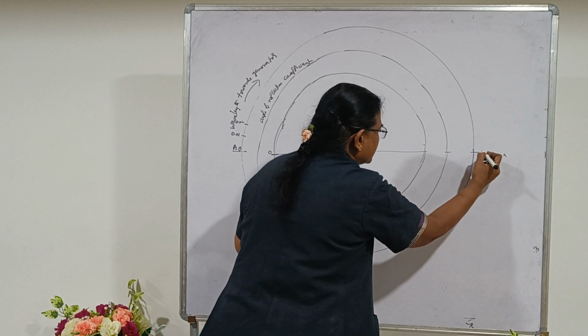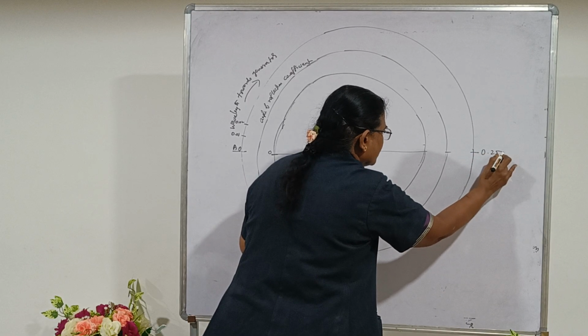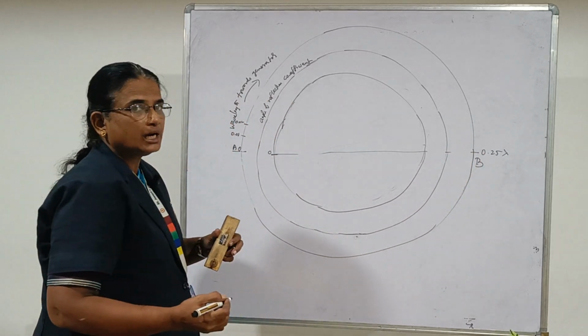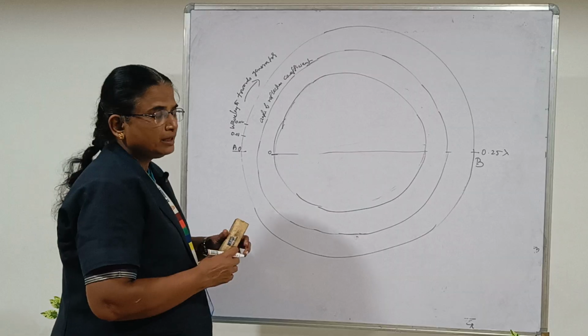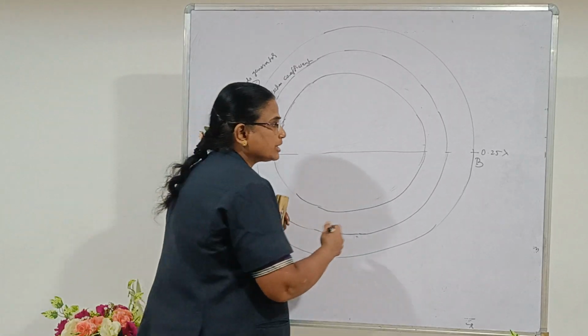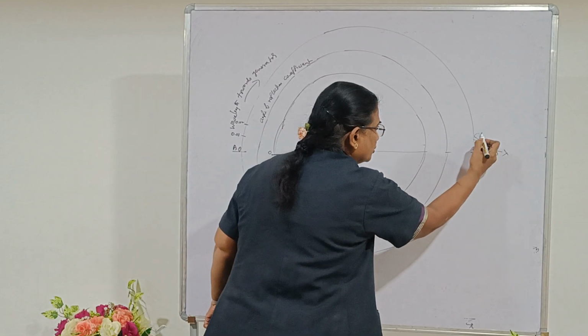The right side of the chart is actually this open circuited end. But when you are going to use the chart as an admittance chart, the right hand side of the chart is designated as the short circuited end. So now you mark this end.